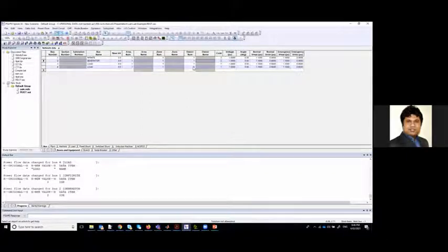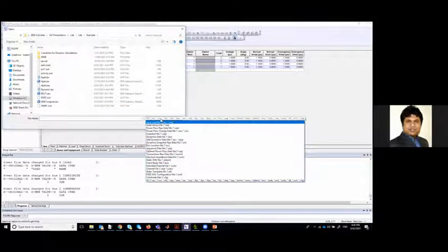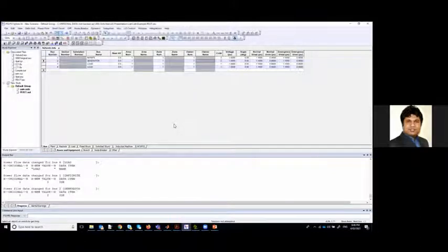Sometimes, if you go to work for industry, and the network data is there, you can straight away open it using the raw data file. If you look here, if I go and click open, there are a lot of different file formats. The first one is called CNV, SLD, and all this. Raw is the normal file that usually equipment in a power network, we can capture through some SCADA system. We can capture the raw data file of the network, and we can straight away use those data just by opening the raw data file. In that case, you don't need to really build this new system.